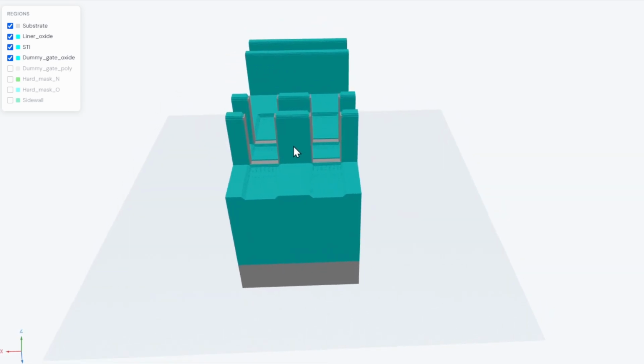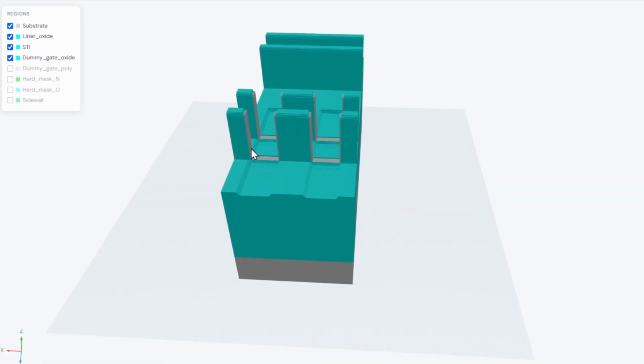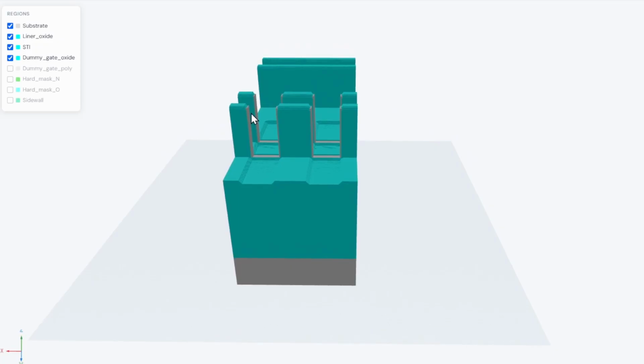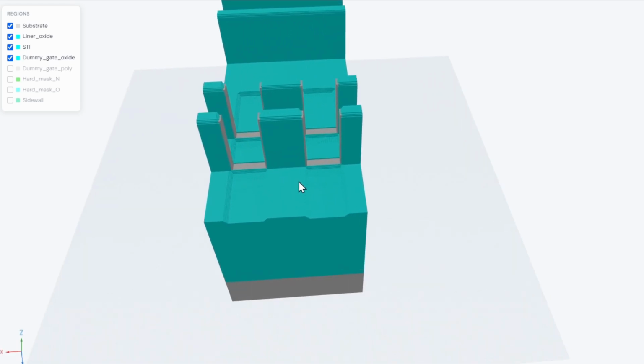If we send silicon or germanium atoms into it, then through the surface reaction between the existing silicon crystal and the silicon or germanium material, there will be growth of silicon germanium all the way on top of this silicon crystal.